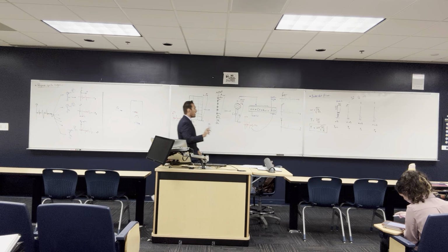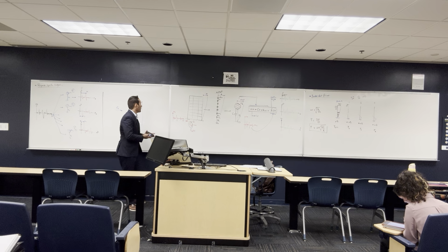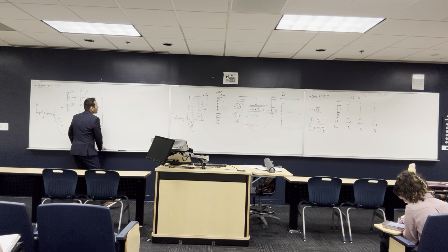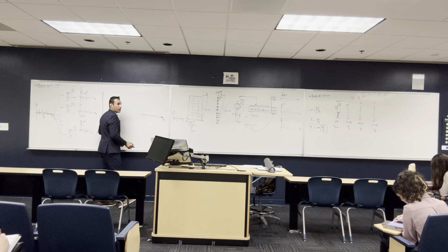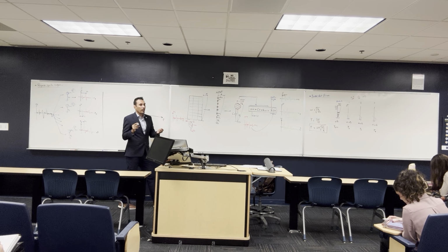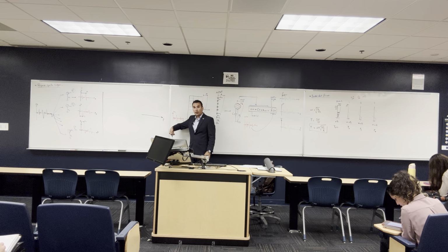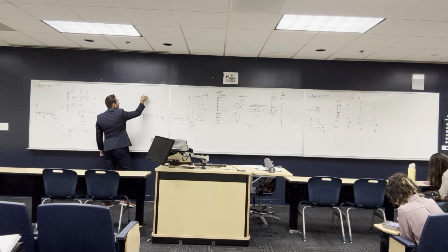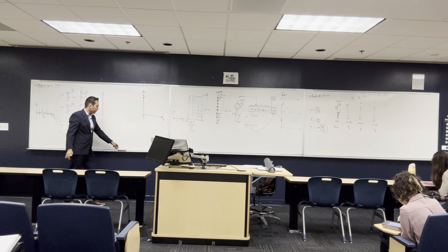Next step, we are going to build a relationship between the characteristic of the building and the performance of the building. They call this curve the response spectrum curve. They put on the x-axis the T, the period of the building. By the way, T is not only time, it represents stiffness, because T comes from the mass and the stiffness. That's the characteristic of the building. I told you this is the fingerprint of the building. And on the y-axis is the response of the building, the acceleration, A. They call it SA, the spectral acceleration.